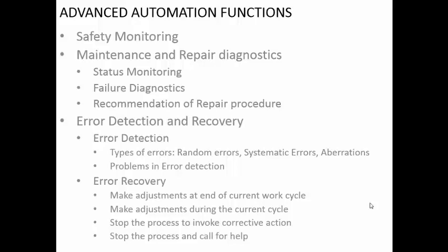Now with respect to the machine, whatever the program is given, the operator may not know the actual things that are happening. So even if the program is giving certain instructions, if the machine is under unsafe conditions, then we say that there is a safety issue, and the machine should stop. Now this can happen when you have a very hard workpiece, the hardness is more than the expectation, it has been loaded into the machine and the cutting process is starting. So a tremendously high amount of force is generated.